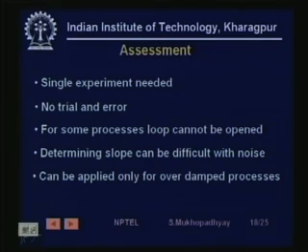When you have noise, finding the slope numerically from data can be very complicated, and you have to use some good approximation procedures. And finally note that this procedure is actually applicable only for overdamped processes, not for underdamped processes. So you cannot take an open loop underdamped process and use this procedure, although you may be able to find some value of K, TD and M. So we need a closed loop procedure,